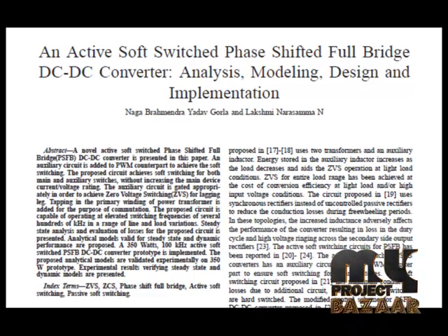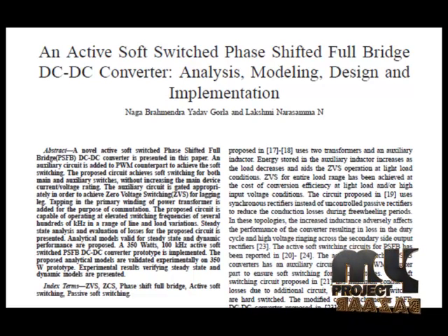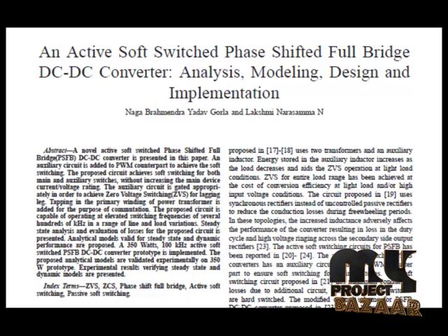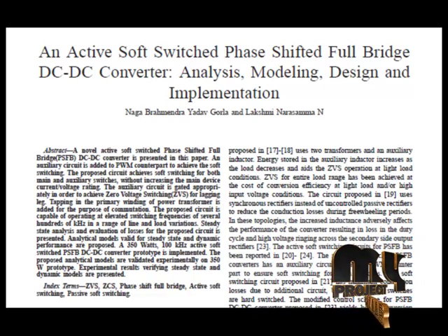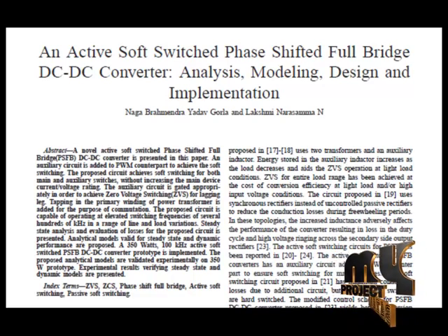The proposed active switch ZVS PWM full bridge converter has two identical auxiliary cells connected to a conventional full bridge. The full bridge zero voltage switched converter is the most widely used soft switch circuit in high power applications. This constant frequency converter employs phase shift control and features ZVS of the primary switches with relatively small circulating energy.